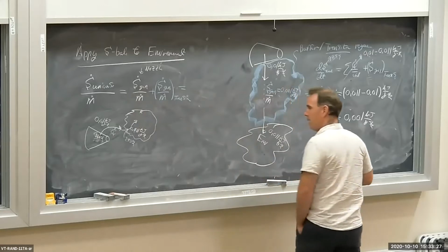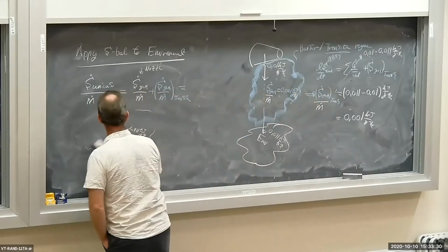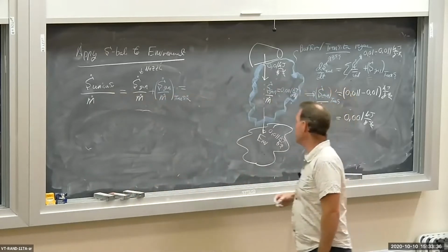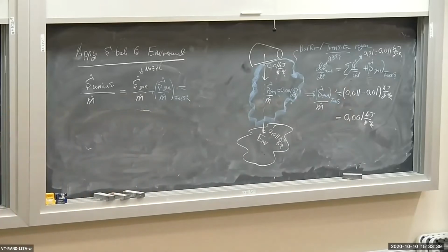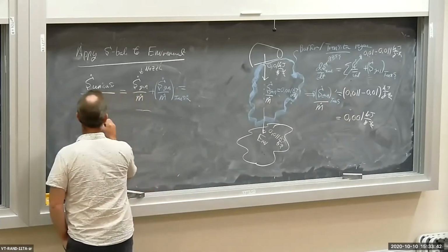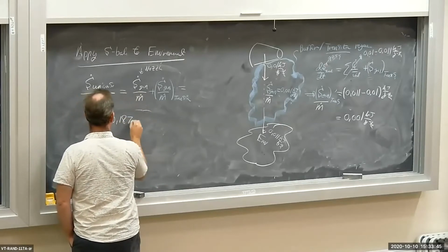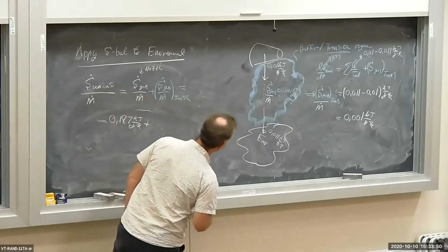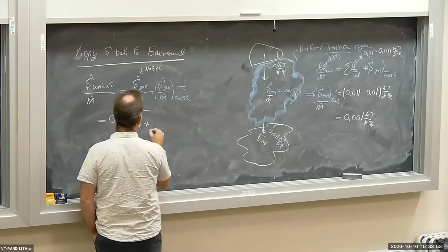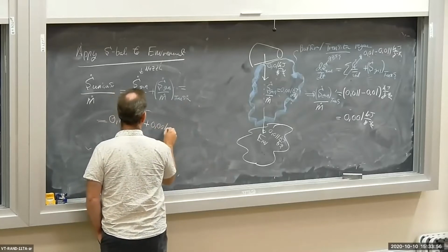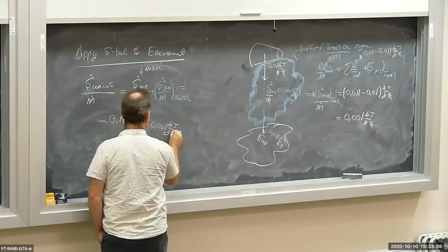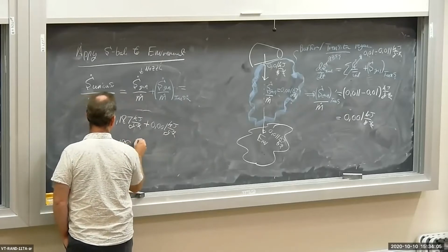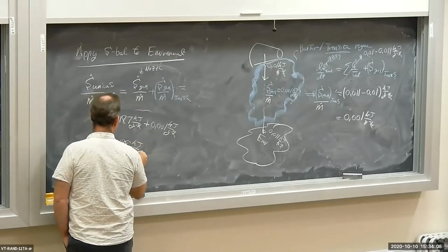And so let me add up everything. S dot gen for the nozzle is 0.187 kilojoule per kilogram degree Kelvin, plus the entropy generated in the buffer or transition region, 0.001 kilojoule per kilogram degree Kelvin, and that gives me 0.188 kilojoule per kilogram degree Kelvin.